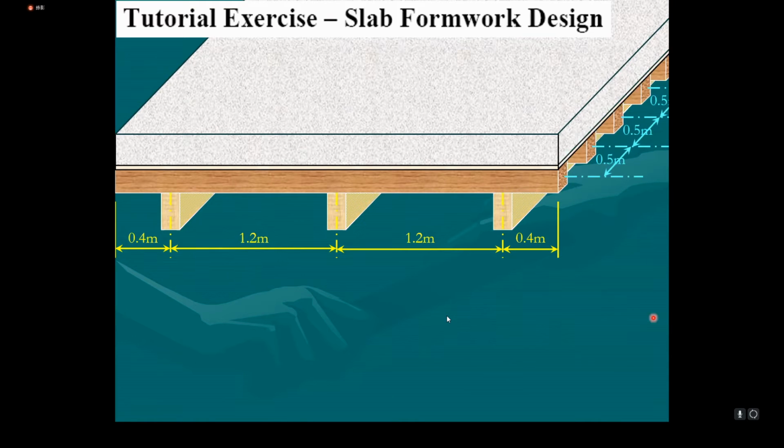Okay, and the joist is supported by 3 barrels. Okay, and the spacing between the barrels, 1.2 meters, is basically the span of the joist. But you have cantilever ends this time. So not the typical load cases, load case 1 simply supported, or load case 2.